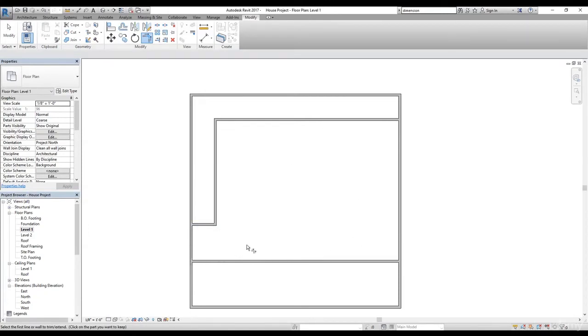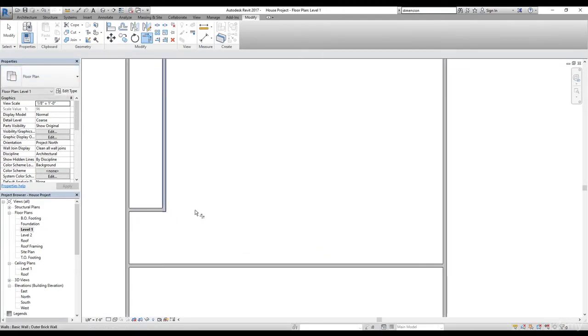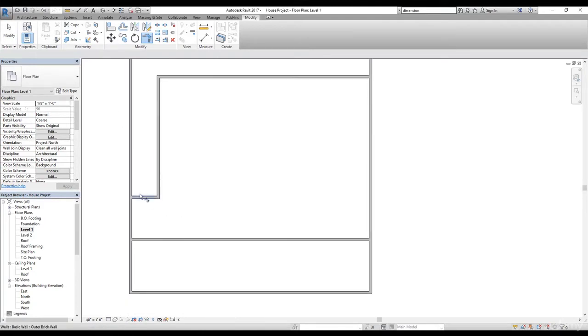Now we have set up this garage area, and now we can use the offset and use our other walls which are going to be inside the house. There's one more thing I want to do here, because this is going to be the outer wall, the same material of the wall. So let's make the garage first, and then we will use the different wall. The garage width is going to be about 18 feet. So I'm going to create another offset. Let's select this offset, and then here I'm going to type 18, press enter, select this wall, click here. That's going to be our garage area.